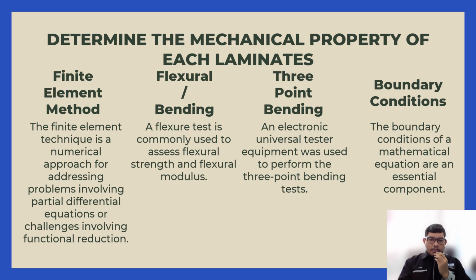Third, 3-point bending. An electronic universal tester was used to perform the 3-point bending test. Balanced and quasi-isotropic stacking sequence laminates were tested first, and then unidirectional. Each test specimen was given a load displacement plot, and every type of composite laminate was evaluated 3 times.